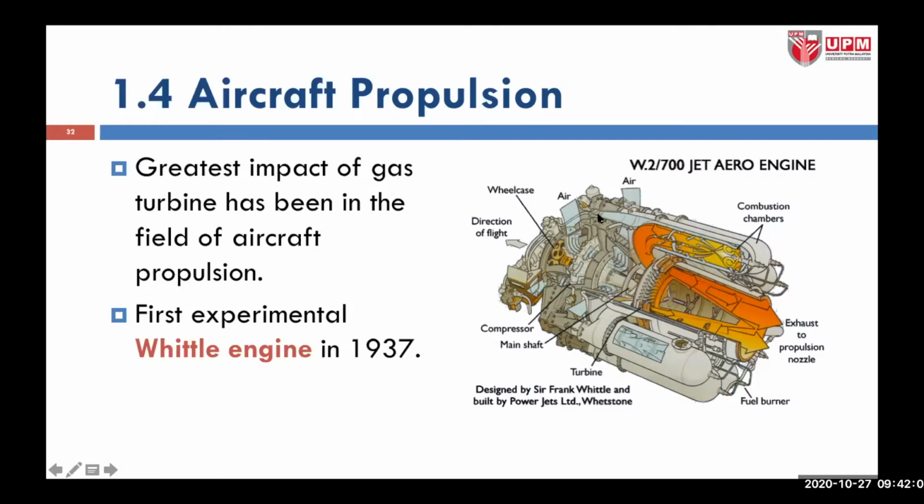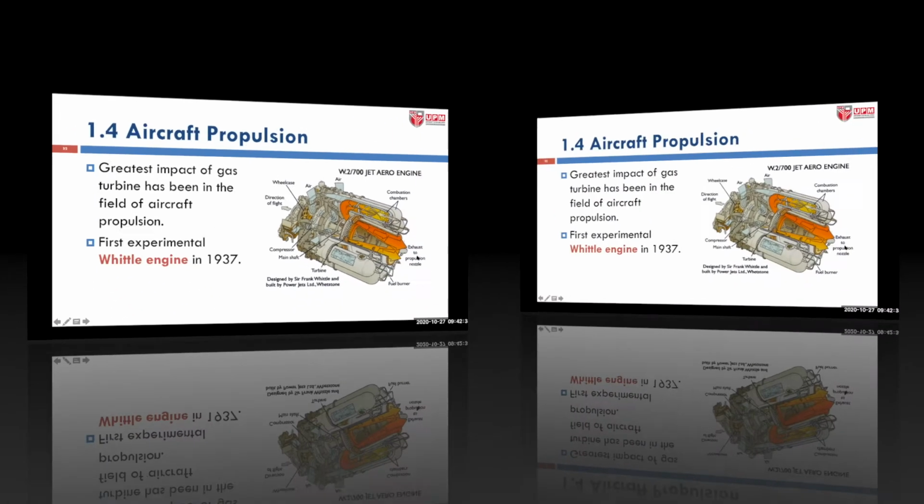So air comes in, is supplied up here, going into the combustion chamber, and then the combustion process takes place and the air is supplied to the turbine stages. There is only one single stage of turbine, and then it flows into the nozzle and exhausts to the environment. It's quite a good model for learning about propulsion for gas turbine engines.